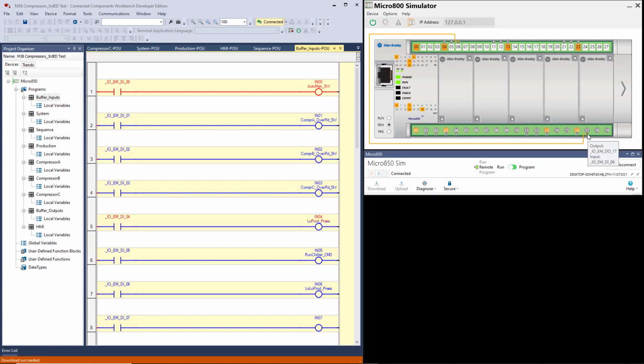We may replace 16 and 17 with an analog input module coming from an analog output module, and then using math and other instructions in our code to take the analog signal in from a pressure sensor and come up with those same 2 values. Obviously, you can do a lot more with an analog signal than you can with a digital signal.